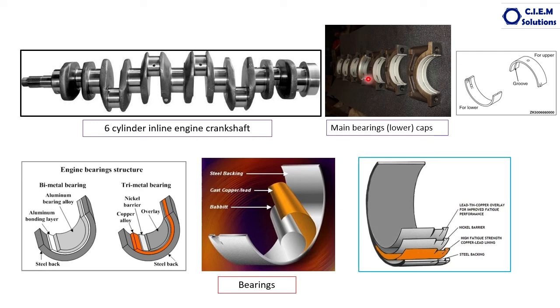Wherever it is touching the block, the block gets damaged. Even for the to and fro movement of the crankshaft there should be cushioning and lubrication. This particular thrust bearing gives cushioning on both sides when the crankshaft floats or moves to and fro. This is the job of the thrust bearing.